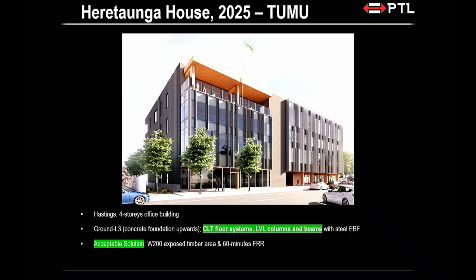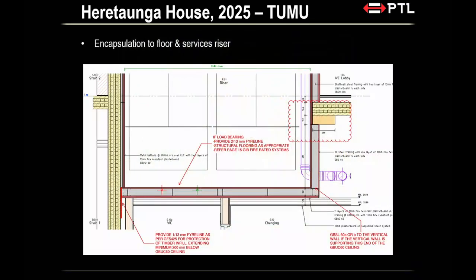16-minute FRR, told my structural engineer, happy days, go off, do the charring calculation, design the connection, column, whatever, all right? So that's it, but still, we have to encapsulate something. So in this particular project, we're encapsulating the floor naturally, and one requirement requires us to encapsulate the back wall of a services riser.